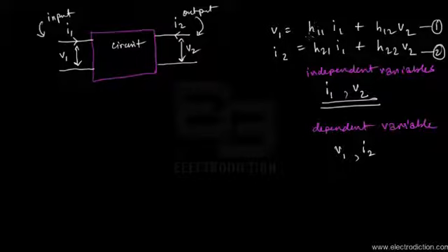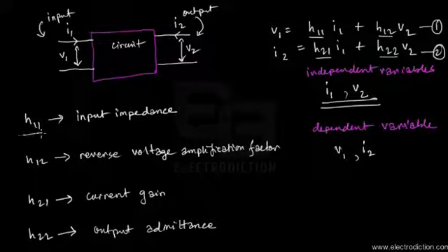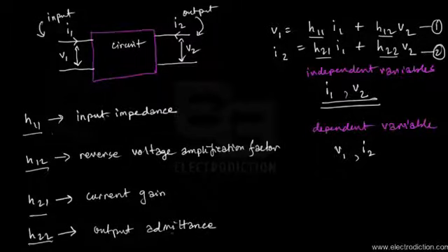All these H11, H12, H21, and H22 variables that you can see over here are the corresponding H parameters that we have been talking about. Over here you can see all the H parameters and what their physical meaning is, given onto your left. Now we're going to treat the transistor, or the BJT, as a two-port network. So let's check out how that happens.